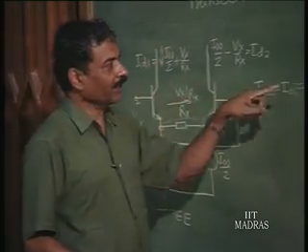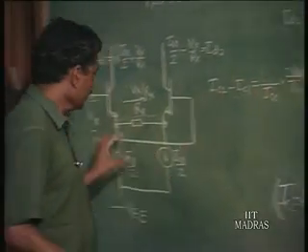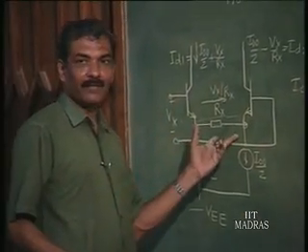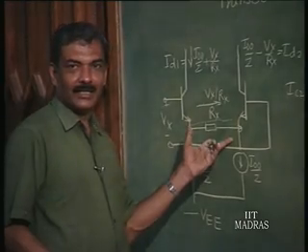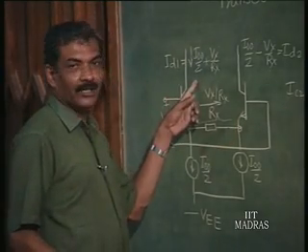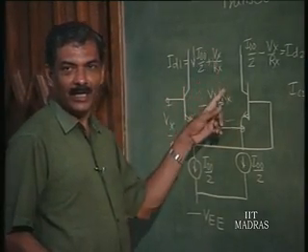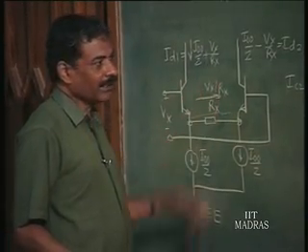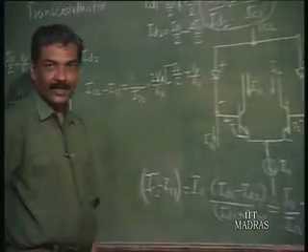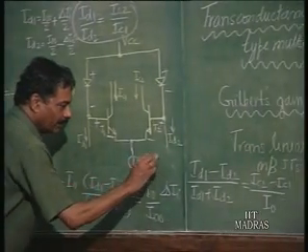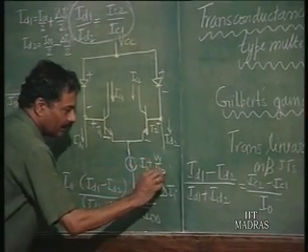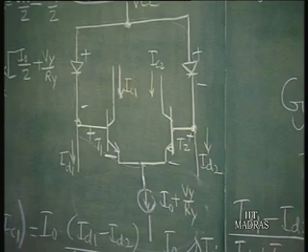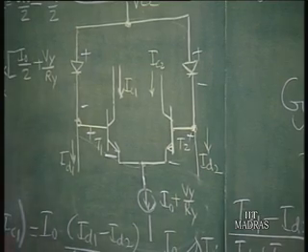We can have a voltage to current converter there also, only thing is it will be Vy here and Ry there. So, that can generate a current which on one side is I naught by 2 plus Vy by Ry. So, this current can be generated. Instead of a current source of I naught, I will simply put I naught plus Vy by Ry there, a current source. How do I get that?